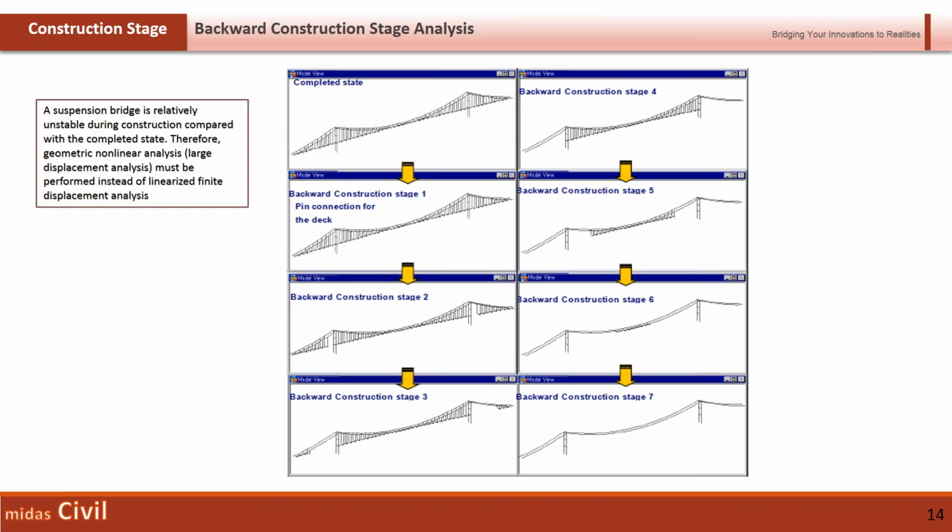So, the thing about construction stage analysis in a suspension bridge is that we have to check how the forces are being redistributed from the beginning. We have the completed state model already with us, so we go by backward construction stages.